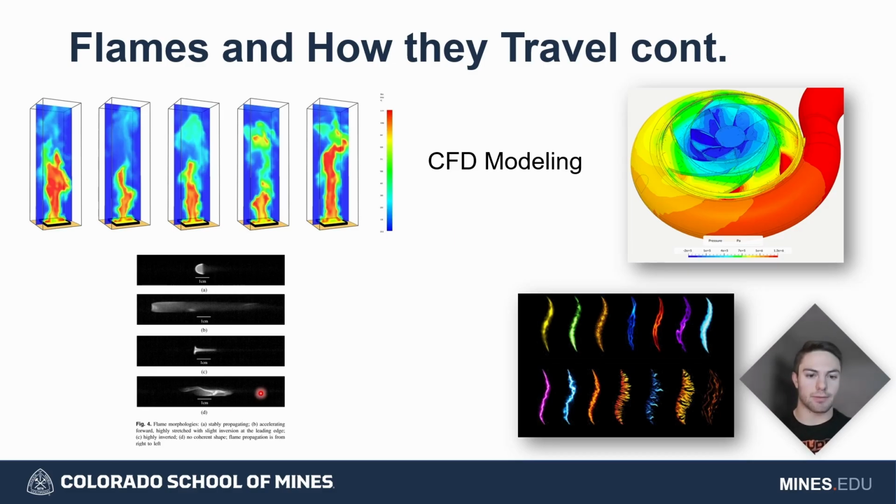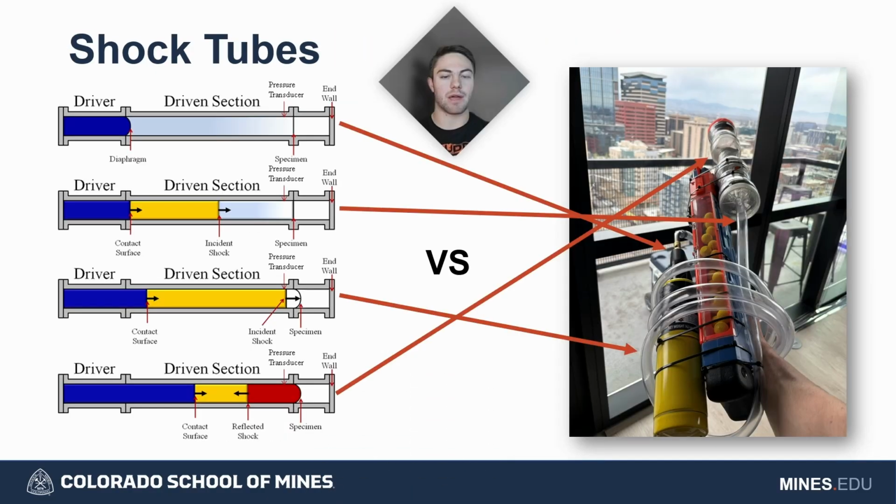model. So this figure shows a laminar flame as it travels through a tube. This nice curve is what it will look like in a tube, and then slowly getting more turbulent. So this is a turbulent flame in the tube, and it will propagate and look somewhat like that as it goes along. Now, based on the demonstration, what do you think the flame front was, before I show you any math in the demo? Was it laminar or was it turbulent? Okay, I really hope that you picked turbulent, but we'll get into that in a sec.